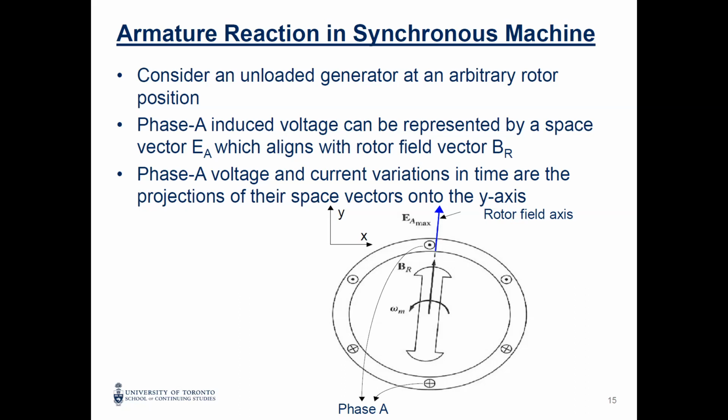You will see in assignment number 2, one of the theory problems that I included: we have armature reactions, how can we reduce the impact of the armature reactions in the DC machines? But in the synchronous machines, it's inherently there, and without it, the machine is not going to operate. So it's something really, really important. It's already there, you don't have to add anything.